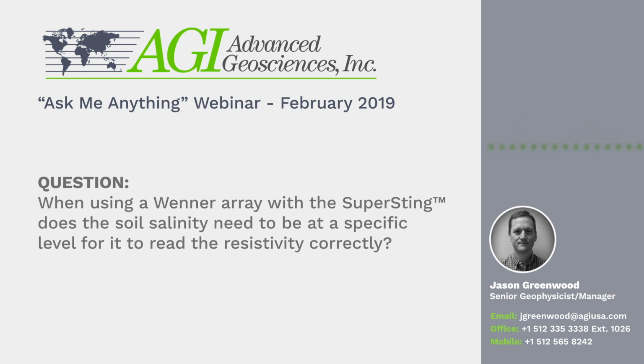It's kind of a worst case scenario, I would say, for this type of work. This is dipole here. Dipole does need typically some filtering, but much higher resolution, much more detail. I could show you some examples of targets where the Wenner array completely missed them. Typically in karst, you'll miss the fractures and you only resolve the biggest ones. So that's just inherent in the geometry itself.